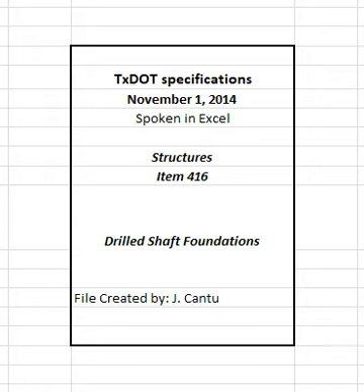Provide a collar or other means of capturing slurry and the top portion of concrete flushed from the shaft for shafts over water. Remove the tube, reseal it at the bottom, penetrate with the tube into the concrete already placed by at least 5 feet, and recharge it before continuing if concrete placement is interrupted due to withdrawal of the submerged end of the tremie or pump discharge tube before completion.